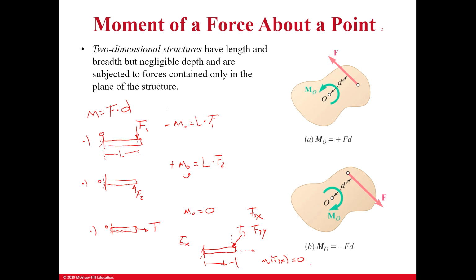Okay? Moment of F3y is equal to F3y times L, and is negative. Okay, so all we're saying here is O could be the point where you want to measure the moment at, could be anywhere. Doesn't have to be the origin, doesn't have to be the fixed point. As long as you know the distance and the force that is perpendicular to it, you're good.